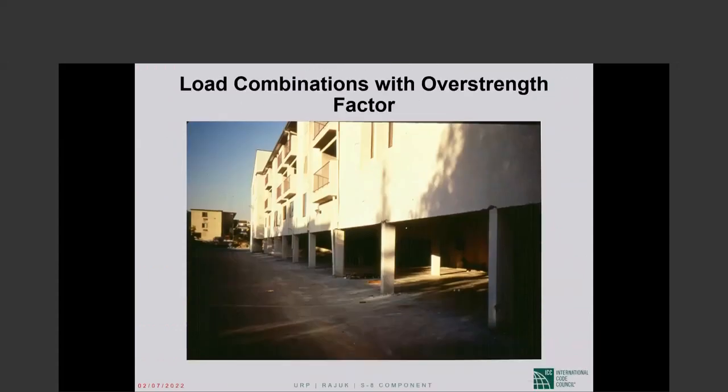these are very, very common around the world, actually. In many parts of the world, the residents of apartment buildings park their cars underneath the building. So the lowest level is open, supported by columns. But then from the next level, you have shear walls, because those are residential units and walls are needed to separate the different spaces, bedrooms and so forth. So this is extremely common, but this also gives you